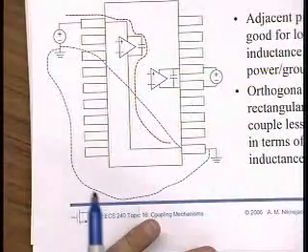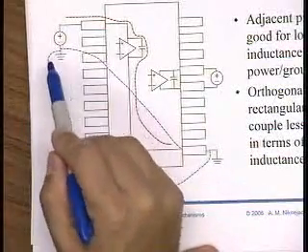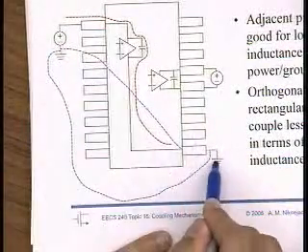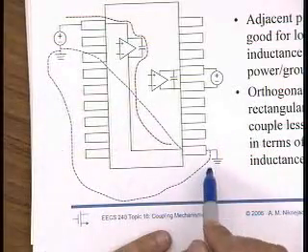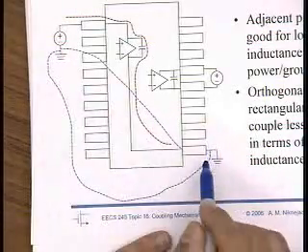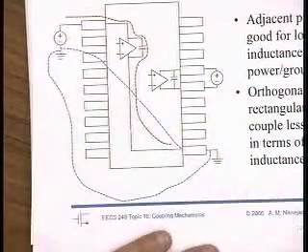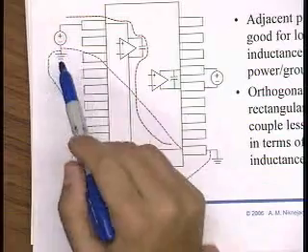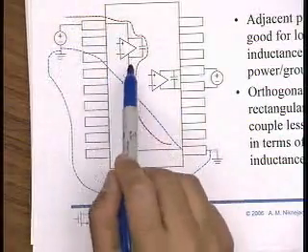And the reason it's a bad choice, as I mentioned last lecture, first of all, what does ground mean? It's a very dangerous thing. It could mean that there's a wire trace on the board that connects these two points. It could mean these are vias down to the ground plane, and there's actually a ground plane. If there is a ground plane, that's the case I've drawn in red. I don't know if that shows up so well.